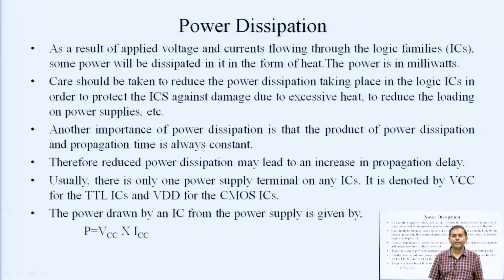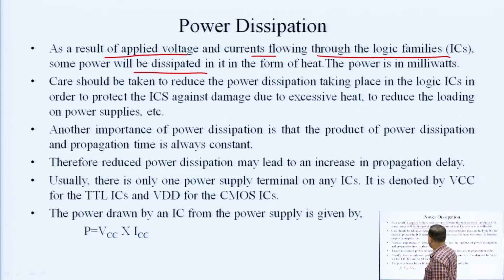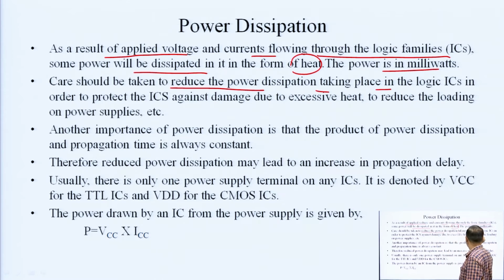Then there is power dissipation. As a result of applied voltage and currents flowing through the logic families, some power will obviously be dissipated, and it will be in the form of heat. The power is in milliwatts. Care should be taken to reduce the power dissipation in logic ICs to protect the IC against damage, because if overheating occurs then the IC can be damaged, right. So, to remove excessive heat, reduce the loading or power supplies.